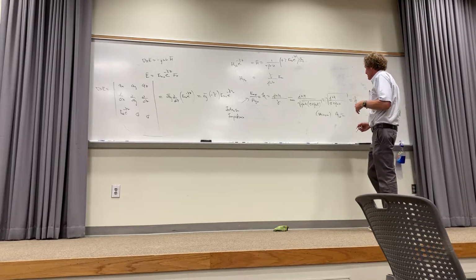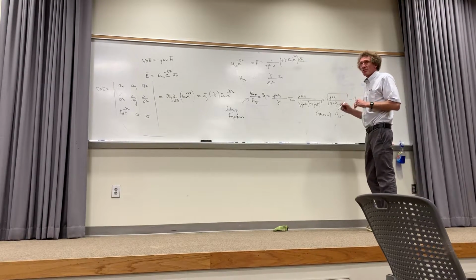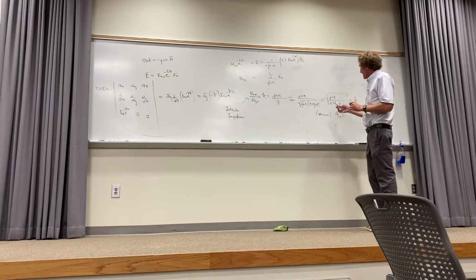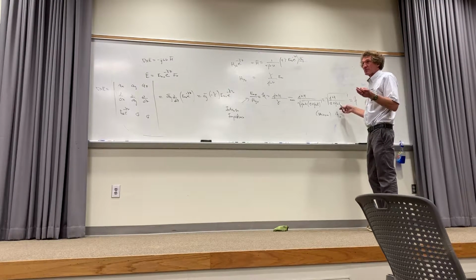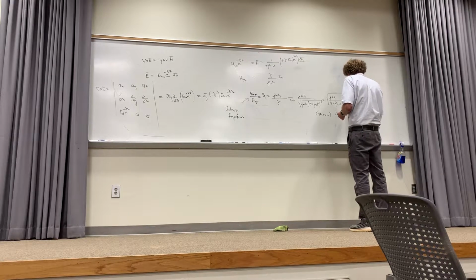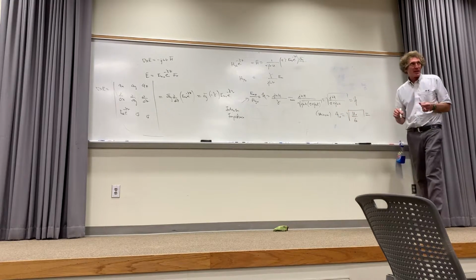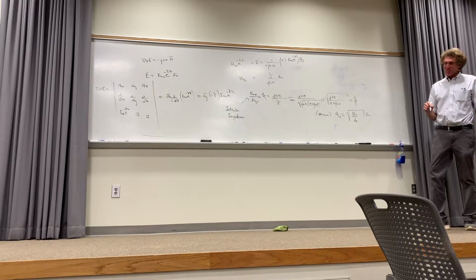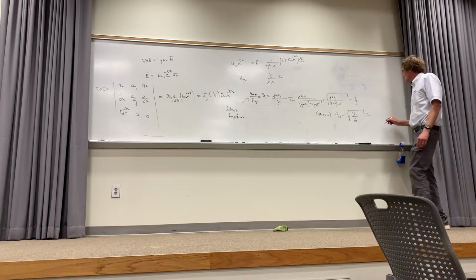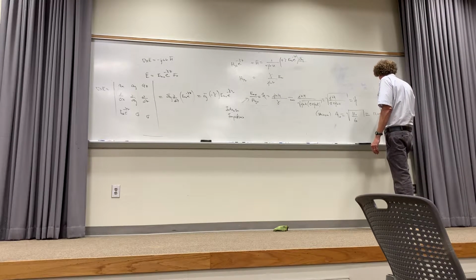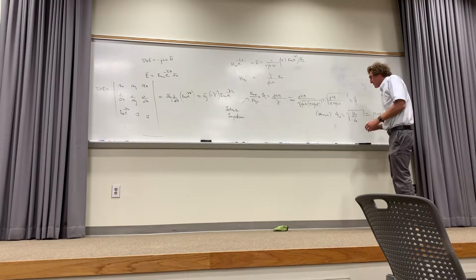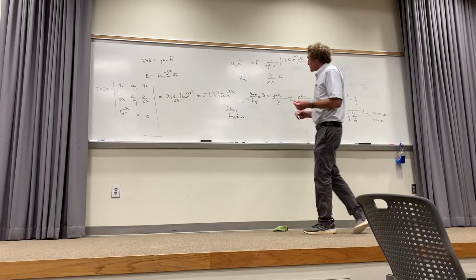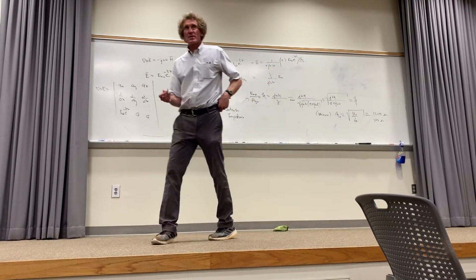If it's 0, then I've got j omega mu, and in free space it's only mu naught, over j omega epsilon. Epsilon in free space is epsilon naught. So I just have the square root of mu naught over epsilon naught. Does anybody know what that is? It is a very important number. The characteristic impedance is 120 pi or 377 ohms. This is very important, and it is the ratio of E to H in free space.